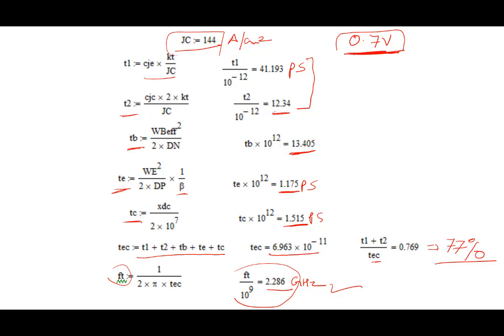Look at all the delay components that are there. You want to make it faster. What would you do? Quickly, if you want to improve the speed of the transistor, which is a dominant component of delay? Emitter junction capacitance, and collector base is not that there, but both of them, let's say if I look at it, they form 77%.